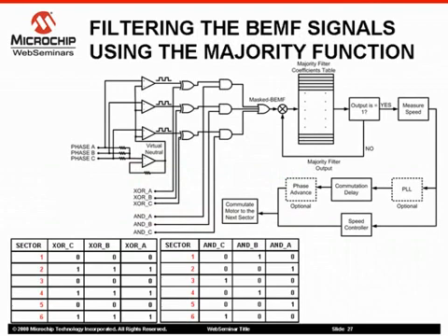The implementation of this non-linear filter is based on a 6-sample window in which at least 51% of the 3 most significant samples should be equal to 1, and the 3 least significant samples should be equal to 0, for the purpose of identifying the occurrence of a zero crossing event in the digitalized back EMF signal.